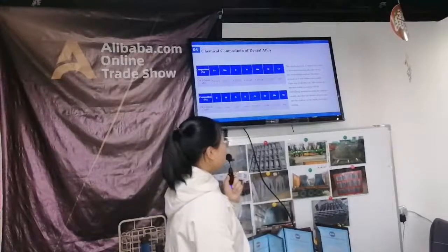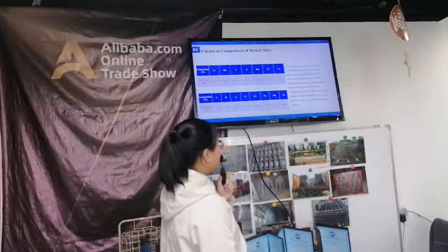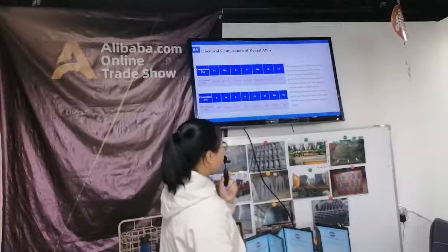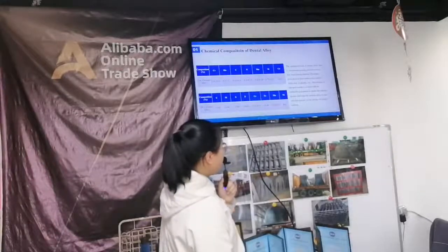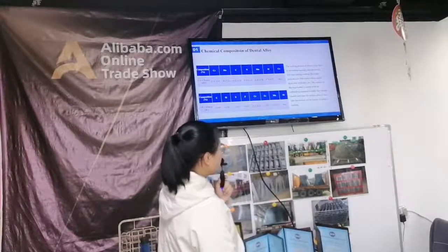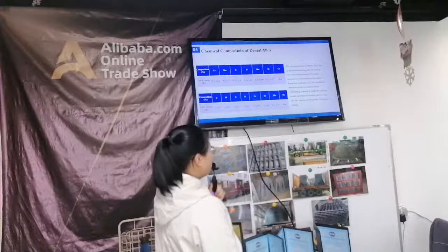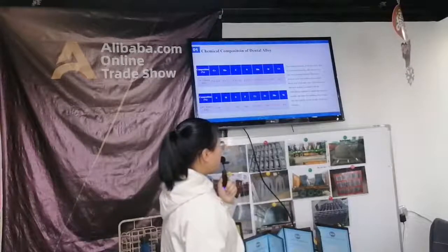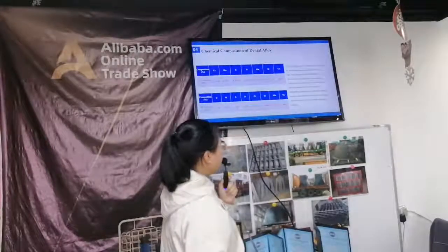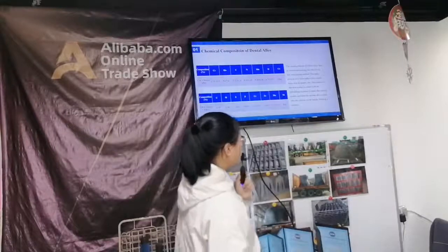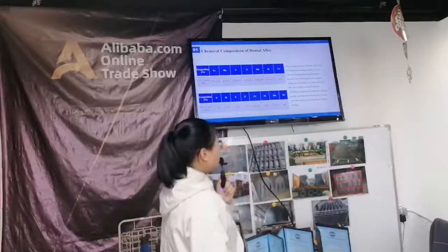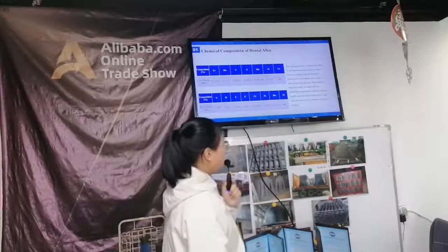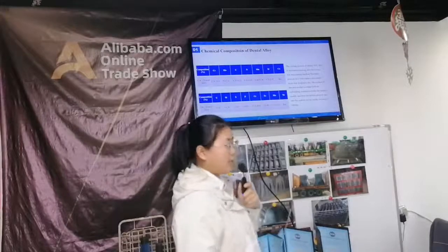The casting process of dental alloy parts is investment casting, also known as lost wax casting method. The basic process is to first make a wax model from wax or plastic. The surface of the wax model is coated with an embedding material to make the casting model, and then the molten alloy is cast into the casting cavity inside, forming a casting.